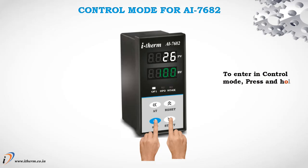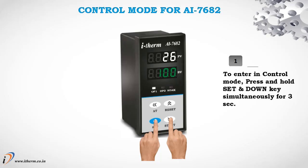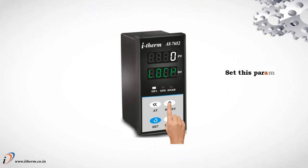Control mode for AI7682. To enter in control mode, press and hold set and down key simultaneously for 3 seconds. Set this parameter to 15 to access control list.